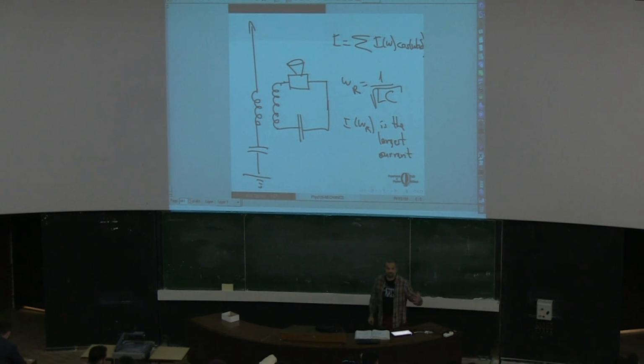So your transmitter, the radio transmitter, we will be studying the simple ideas about radio transmitters on Thursday and next Thursday. So they broadcast their signals at a given frequency or close to a given frequency. And you just adjust your receiver so that your receiver will also have a resonance frequency right at that broadcast frequency. And once that is satisfied, the current running in your circuit will only be sensitive to that resonance frequency. And so from the speaker, you will just hear the signal from the radio station that you would like to listen to.